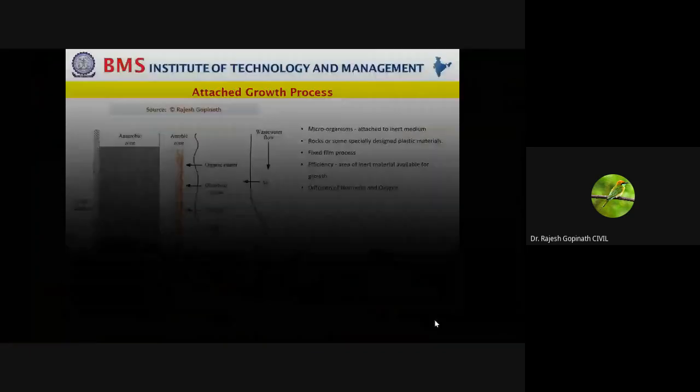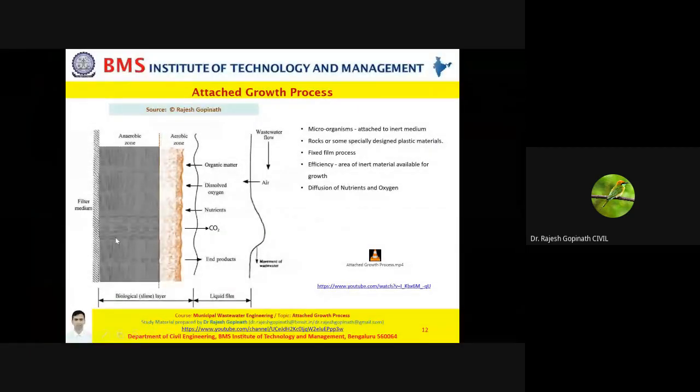So, what was I trying to tell you? Okay, sloughing is a phenomenon. Sloughing is an attribute wherein these microorganisms which are present very close to these surfaces, since they lack access to food, since they do not have access to nutrients, whether they are aerobic or anaerobic, when they are unable to feed, multiply, reproduce, they eventually die. When they die, this entire portion will fall off. This entire portion will come off.